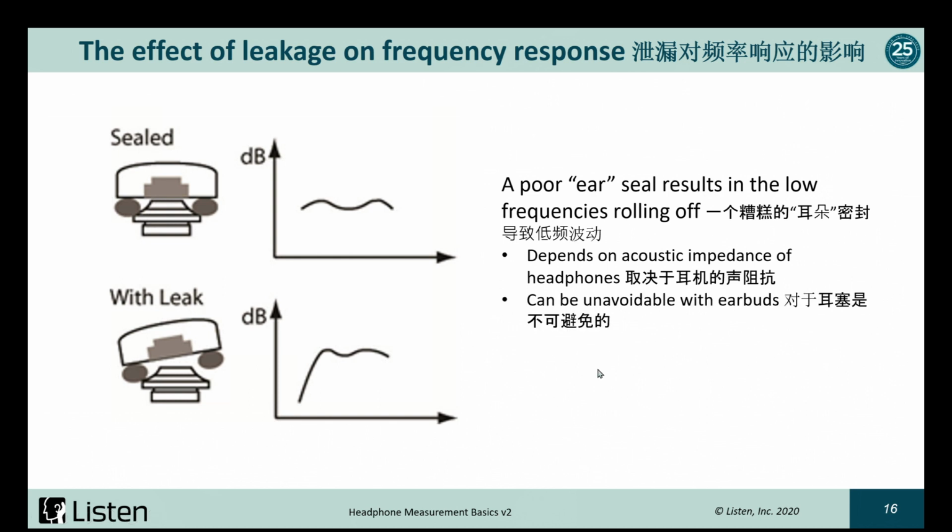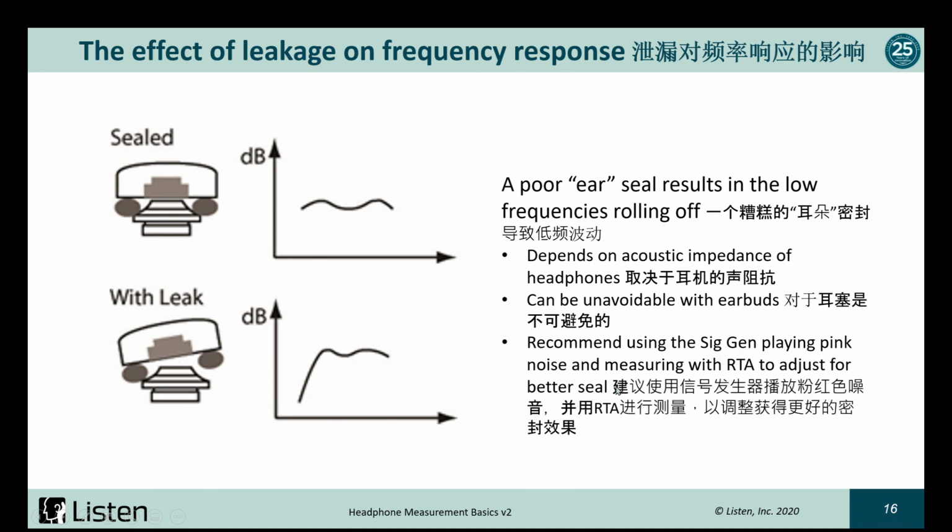But with earbuds, it's pretty much unavoidable because they just kind of dangle inside your pinna, unless you want to hold your finger there and try to seal them, which I don't think you probably want to do. They're particularly problematic for getting repeatable measurements and good low frequency response.